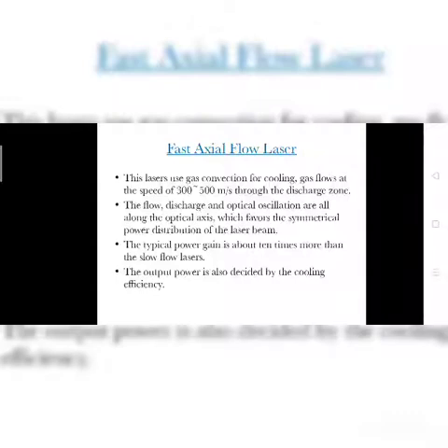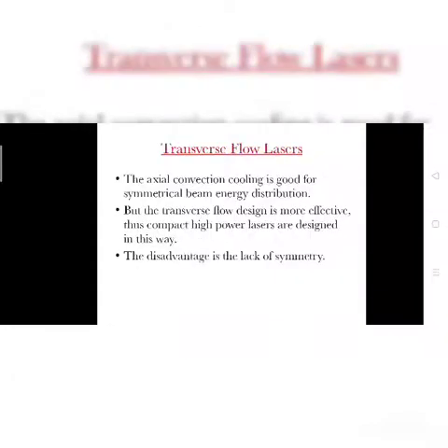The output is determined by the cooling efficiency only. Then the transverse flow laser. The axial flow cooling is good for a symmetrical beam energy distribution, but the transverse flow design is more effective for a compact high power laser design. The only disadvantage is the lack of symmetry.